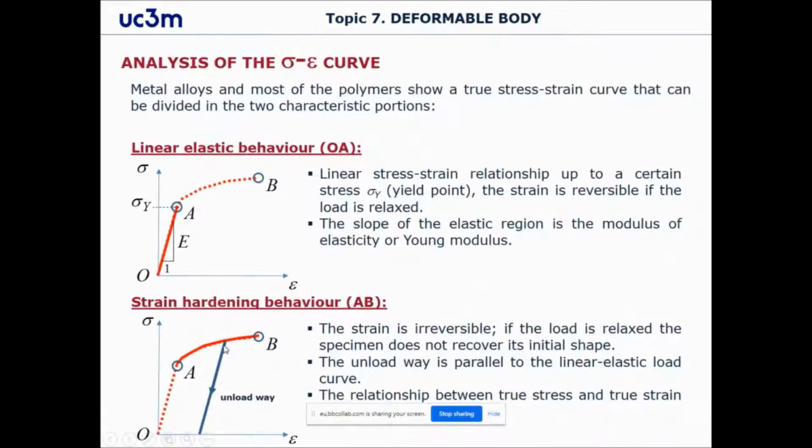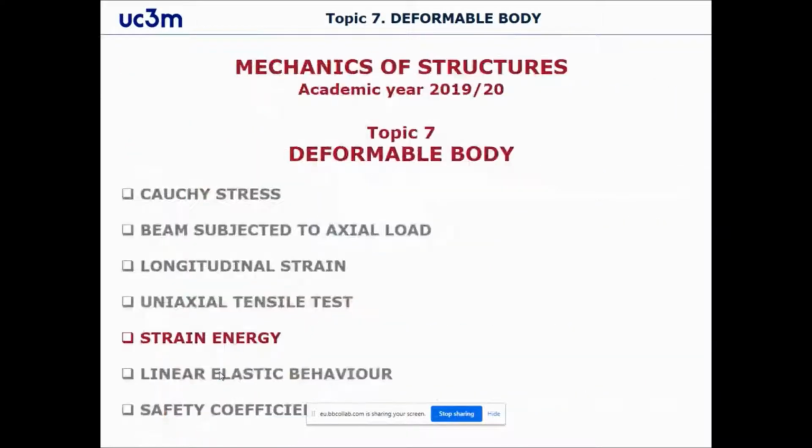So it's important to notice here also that once we unload and load again, for example, once we have reached the plastic stress, the material is going to recover and is going to come back using a path that is parallel to the initial linear elastic path. What it means is that the material is going to return all its elastic energy, it is going to be recovered, and for that reason, it's going to take this path that is parallel to this line. So in other words, the Young's modulus is not going to change because we have passed the yield zone, right?